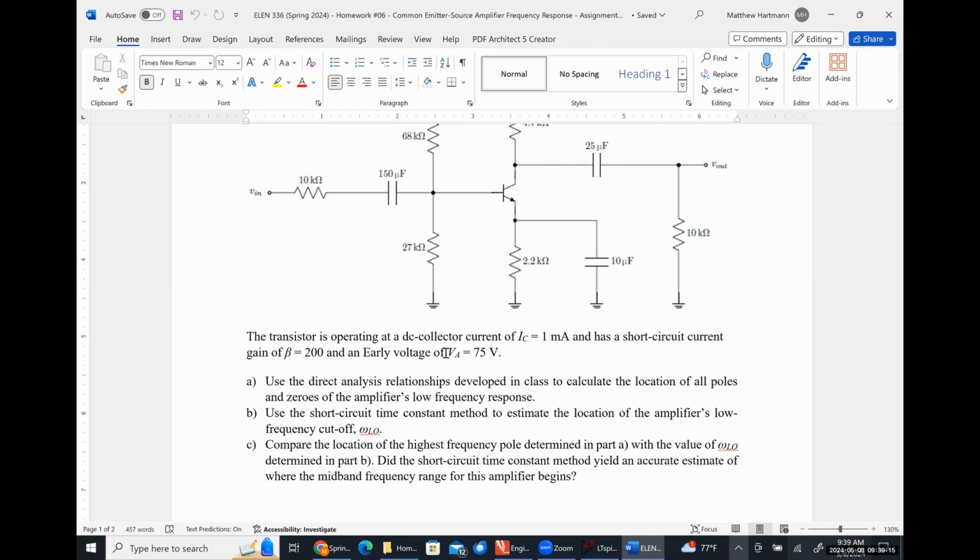Or effectively your device would be working as a diode. So that's a terrible assumption to make. If you were going to make an assumption about anything, you should assume that VA would be infinite, which means your slope would be flat and your collector current would be a constant thing. I understand what you meant, but numbers and all of that kind of stuff technically do matter, even though I'm just as bad as you guys about remembering to put them down. So anyway, for this first problem, you have an early voltage and all of that kind of stuff.